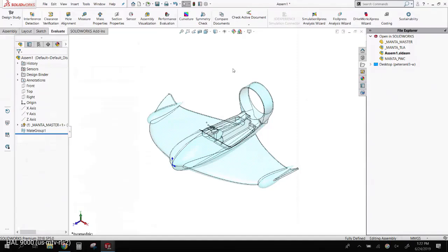It will show up in your file references. Yes, so someone asked a question, does it show up in the file references? It definitely brings in that part file. And what I did in my large assembly was I used it so that I knew when I was putting components in that I wasn't outside of the scope of the design that I was trying to make. But when I was done, I just suppressed that. So it's in my assembly so I can quickly get to it, but it's not sitting there taking up resources, rebuilding all the time.